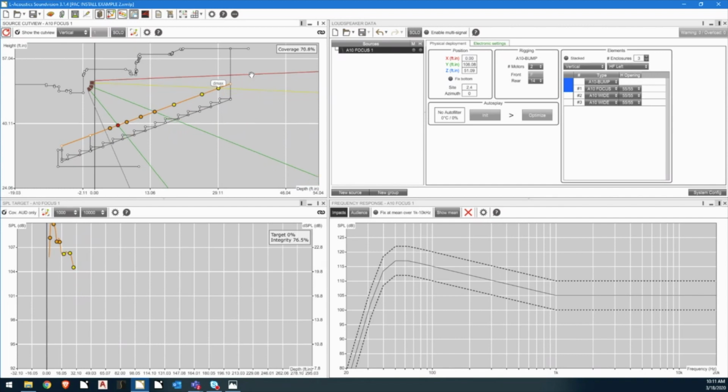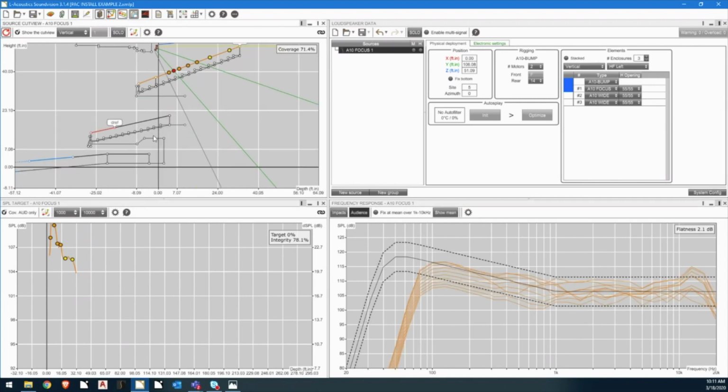Next thing I'm going to do is hit the site angle, right? I want to pan it up just slightly so the on axis of my top box is just overshooting the back of the balcony. And I can set my auto solver's maximum to hit there. Now what I can do is drag in my reference point and my minimum coverage.